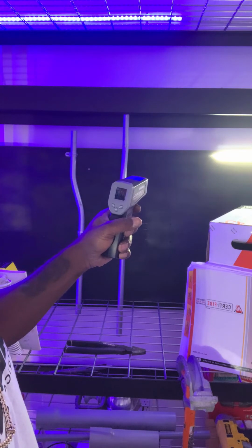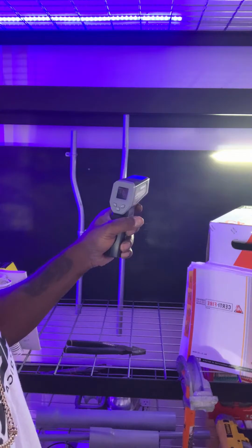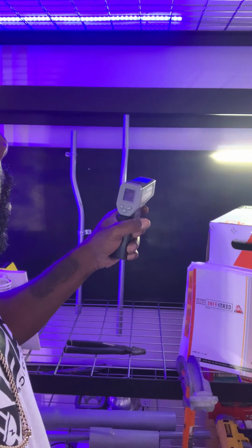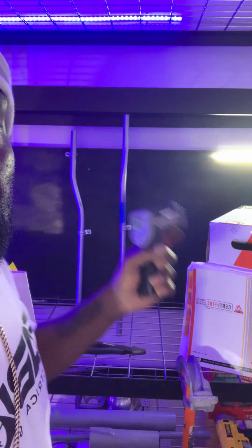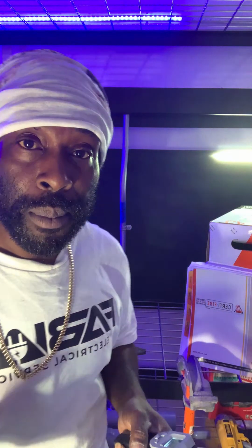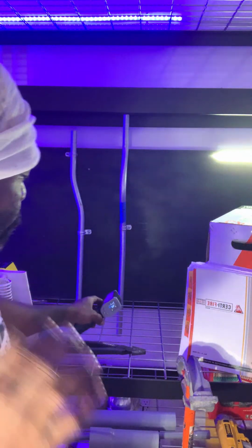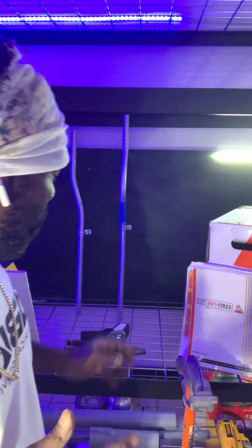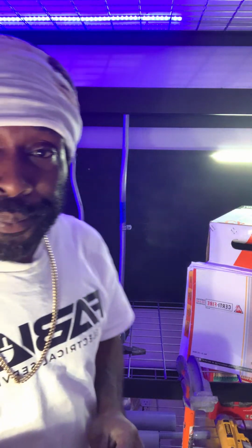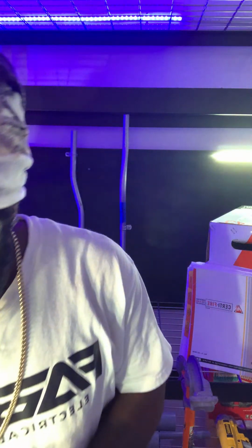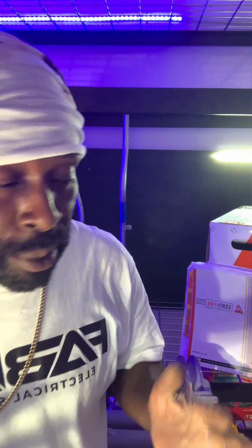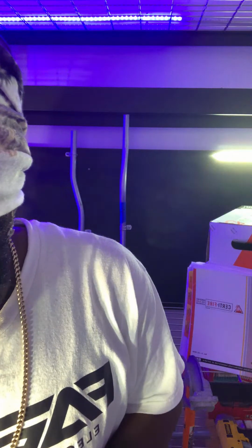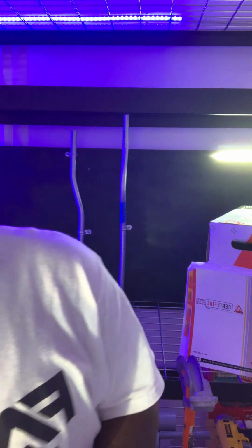I'm scanning for heat, and you can see it's rising, it's rising, it's rising. So that's how I go about scanning inside of the actual conduit. So very important. Again, when it comes to OESC, so what we're going to do now is